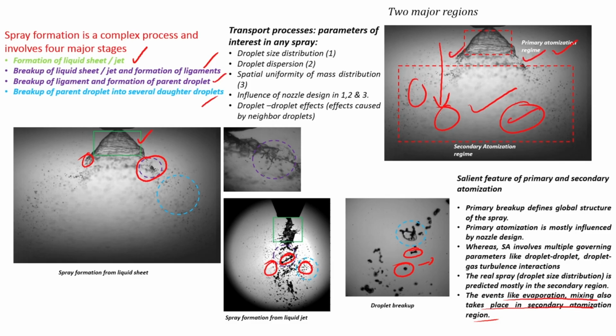It starts to become important in this zone because evaporation, as we already learned, is a very slow process, and these breakup processes are very fast. They can be on the order of microseconds. The breakup process can be very, very fast itself. These nice pictures show how the droplets break up, and they are not spherical. As we said, they are like this or like that, all kinds of shapes.